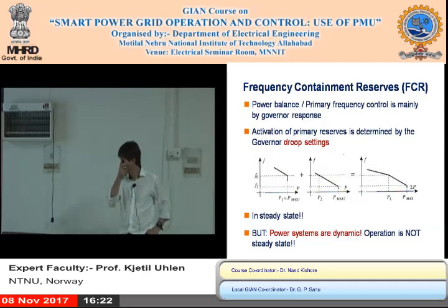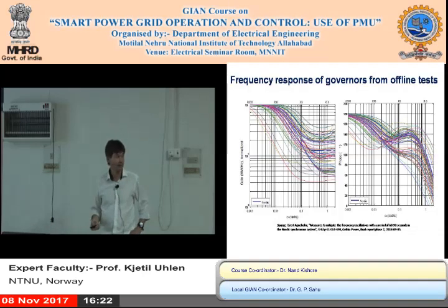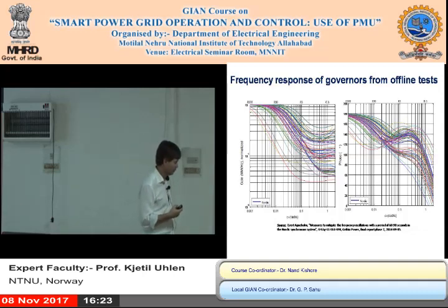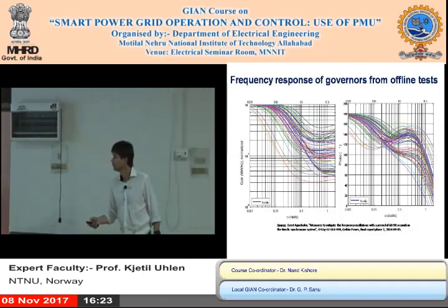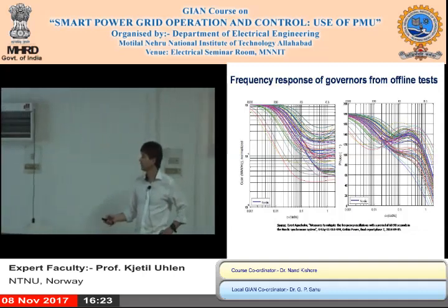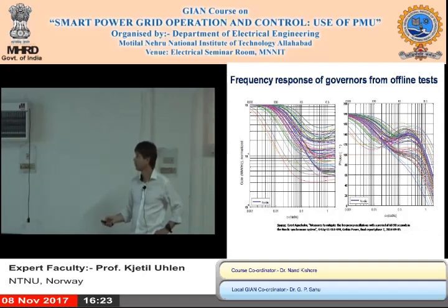So what one can do, what I did in the Nordic, the TSOs in the Nordic power system, is that they went out to measure a lot of things, and they could measure the transfer function on generators from frequency input to active power, and they could see the magnitude and the phase angle.